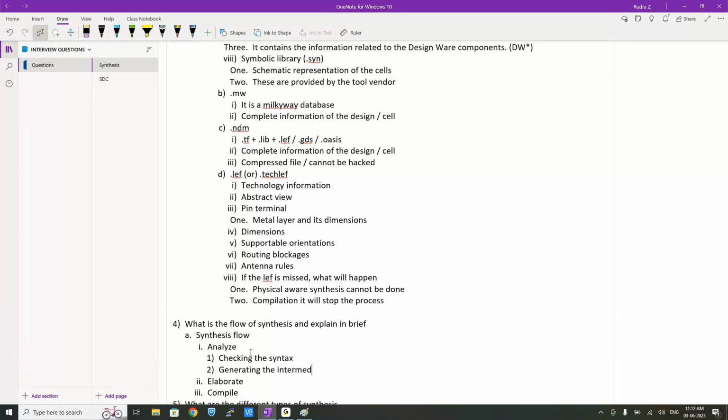So in this particular synthesis flow, there will be a separate temporary directory created. For your provided design, for the run which we are going to be performing, we will store all the intermediate files into that particular temp directory.